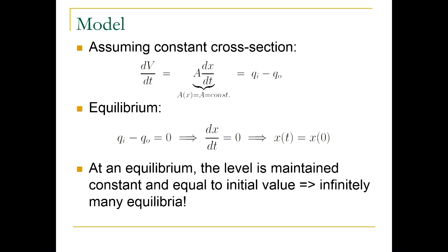If inflow is equal to outflow, I can maintain this level constant, right? Now, obviously, I didn't tell you anything about how to regulate Qi and Qo to achieve this. So if I have pumps on both sides, I can actually totally regulate them as I want. Then the outflow would not depend on the level of water in the tank, because I can regulate the pump, how it works, how much water it takes out. And I can just close it down. So I can make Q outflow like 0, right?